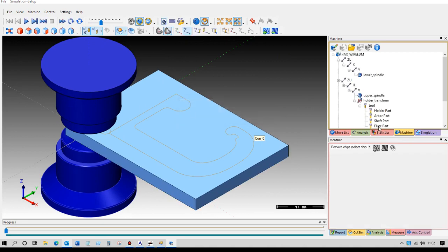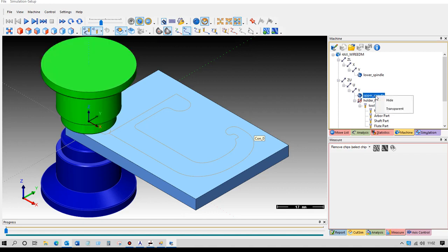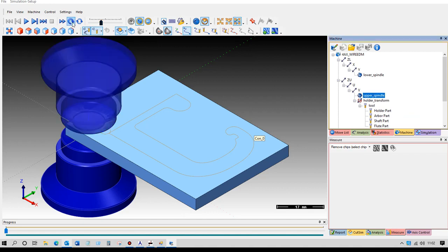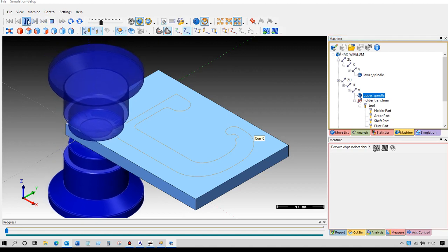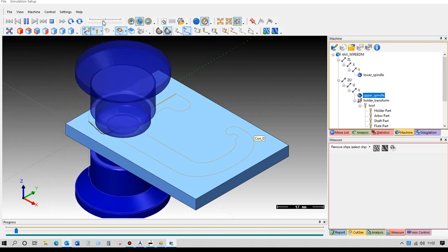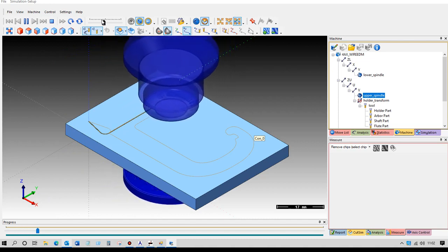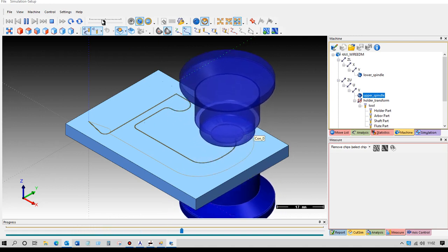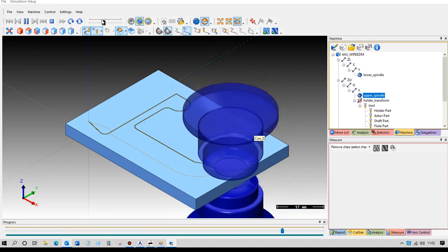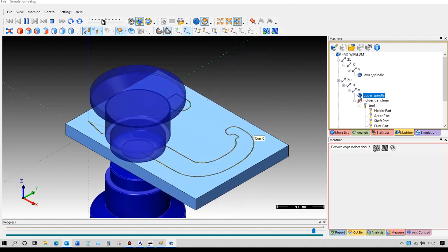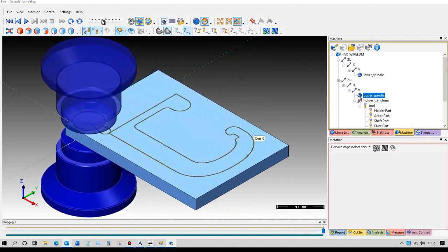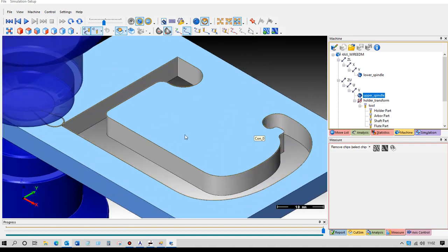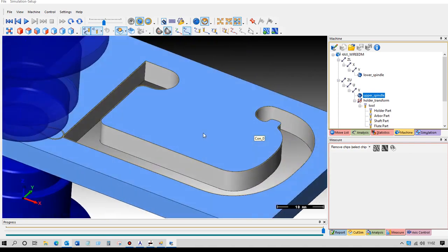This is the top and bottom wire guides, but if we want to, we can come across here and we can make those transparent, and we can just replay the toolpath. We're not going to see much difference here to what we did in the standard wireframe, but if we're using tapered cutting or 4-axis work, obviously we'd see a better representation of how it's actually going to cut. And if we want to get rid of the center shape there, we just click on it so we can see that there. Okay, so that's how we produce the part for that file.